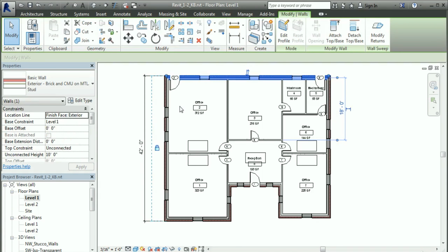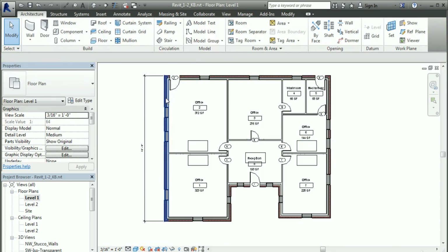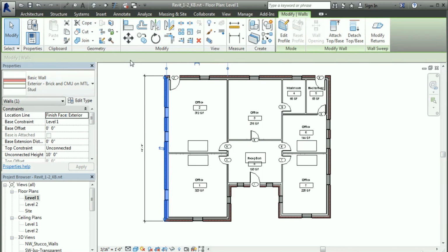Now I can pick the dimensioned wall at the back of the building, and the only dimension that we see is a temporary dimension here on the far right, showing a dimension from the back wall to this middle wall. If you don't see any dimensions, check for an Activate Dimensions icon on the options bar. That normally only appears when multiple objects are selected. Here it is now. And if I choose Activate Dimensions, it shows all of the dimensions that are modifiable for those elements.